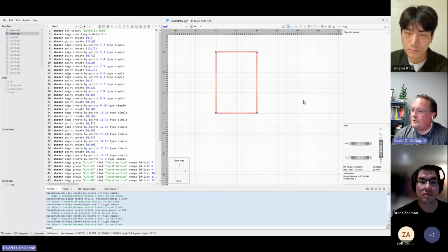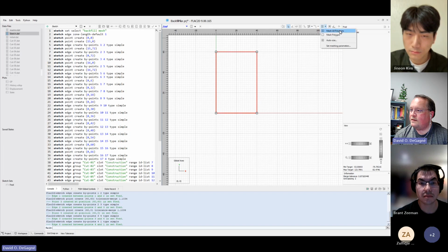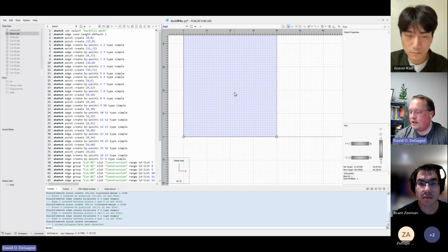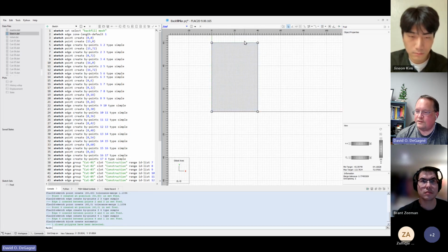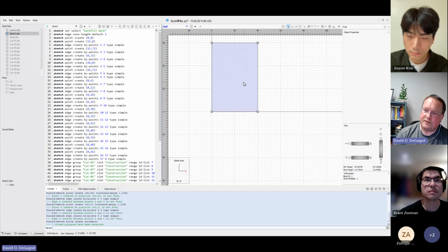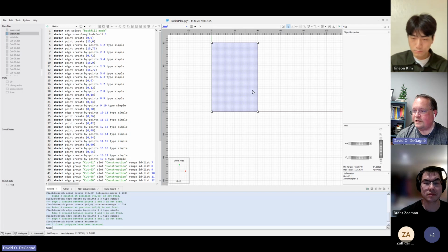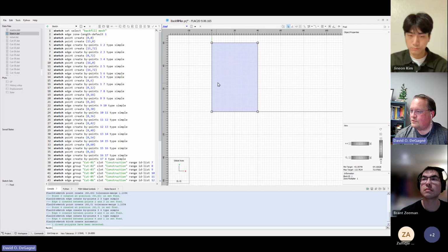And then if we just want to keep it as simple as that, that was our model. We can go in here and then we can mesh all polygons, and we get a simple mesh. It's a very simple model, so everything's just little quads. If we had a slope, essentially it works and tries to generate a hex dominant model. So you'll have mostly quad zones, but you may have some 3-sided zones as well.